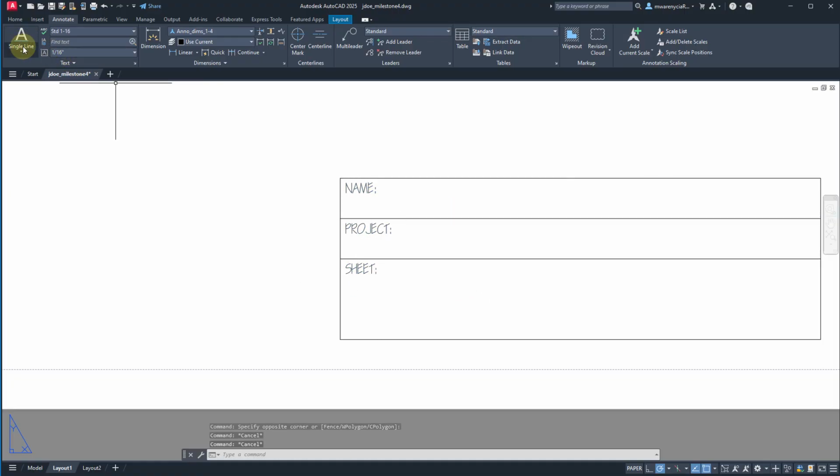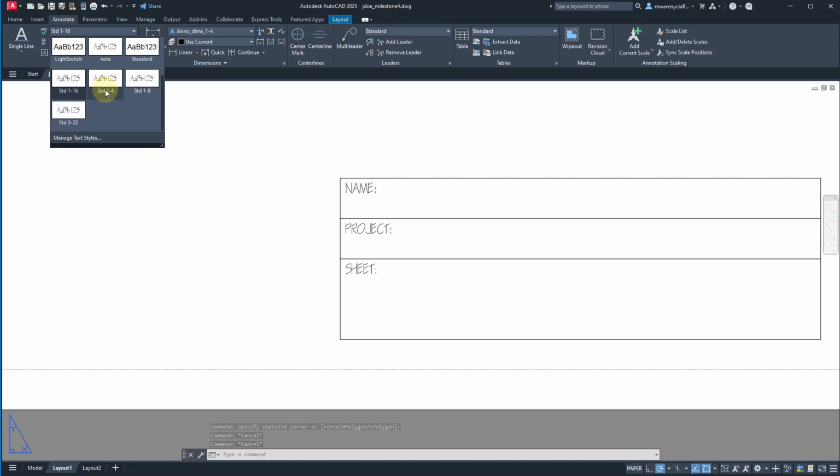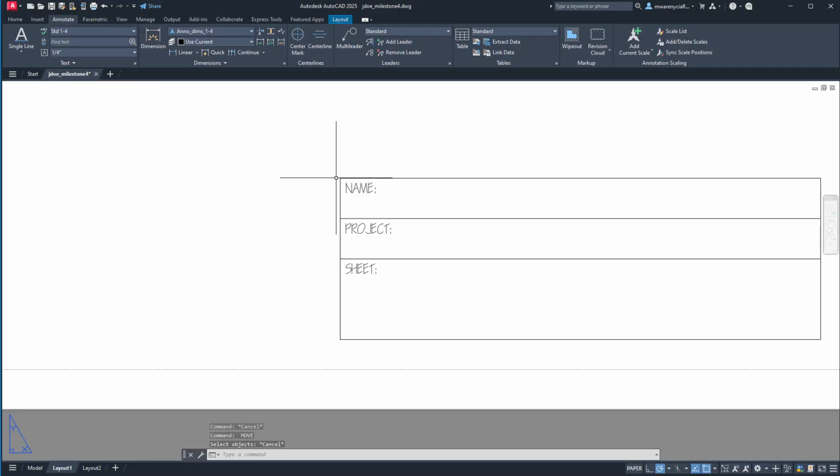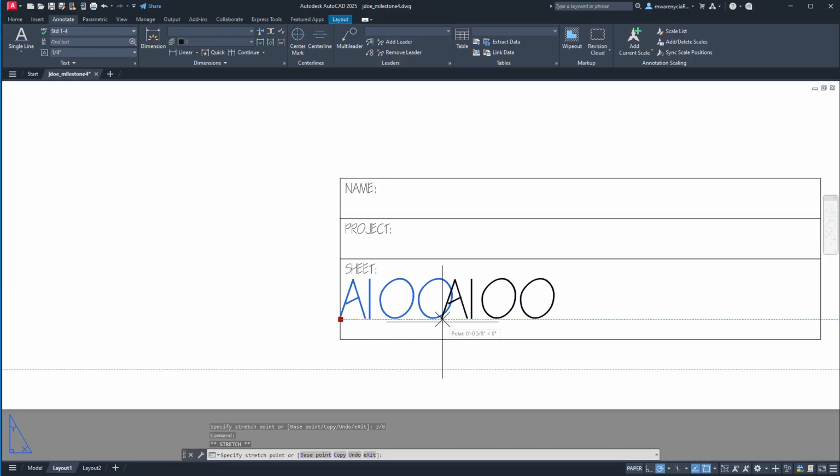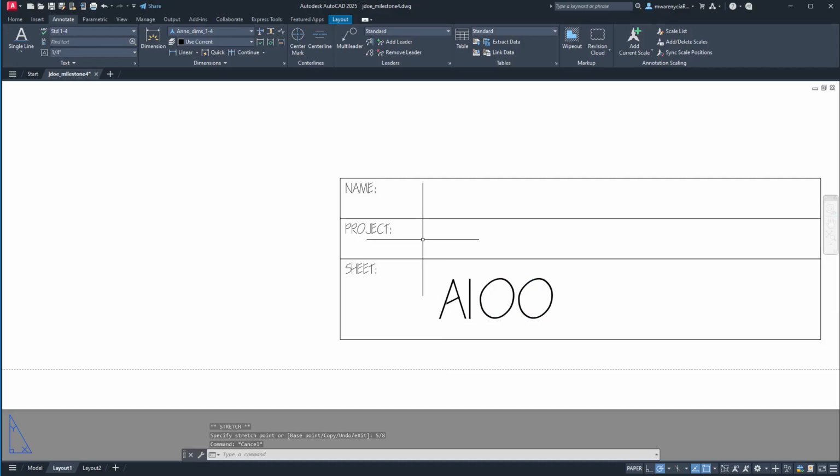Next thing I'm going to do is select them all again. Actually, let's not do that. Let's do another single line, but this time we're going to step it up to 1/4. Text, start here, again, draw it across. Oh, sorry. We'll go with the 1/4. This will be our page number, so we'll move this one down here. And then, again, it's 1/4 inch, so we're going to move it down 3/8 right there. And that should center that right there. And then we'll move this over 5/8, looks like would be good. We'll switch back to our 1/8 inch.